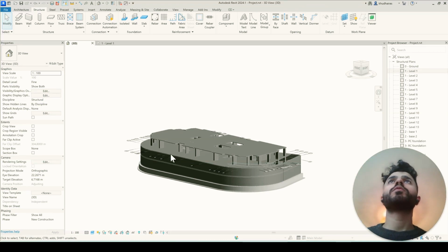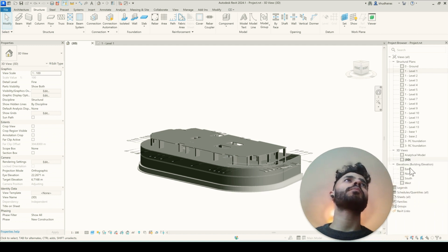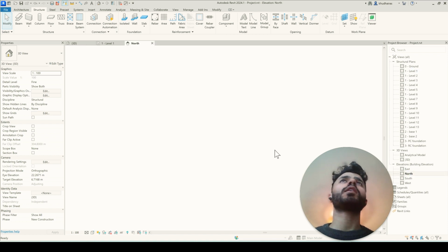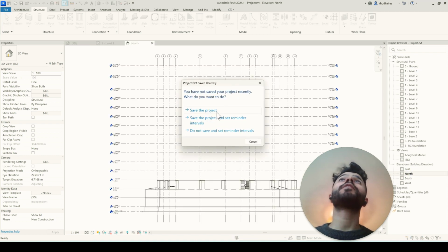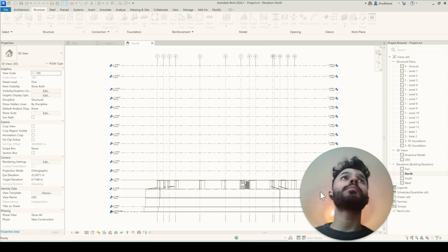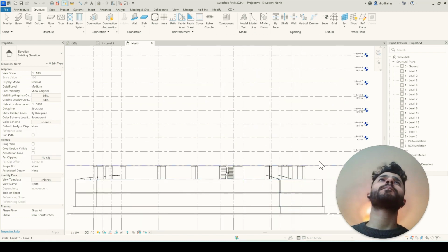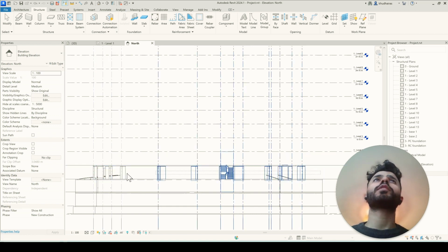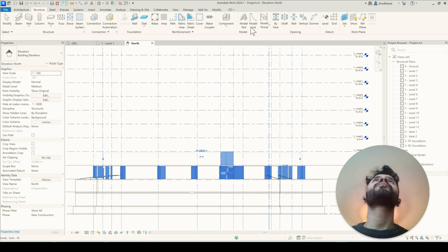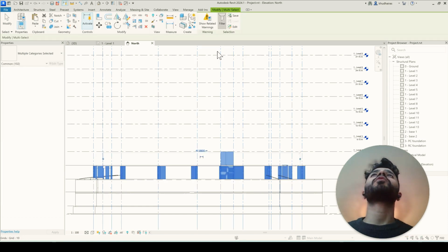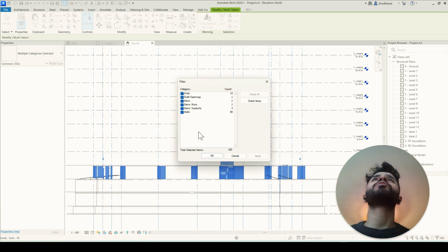Okay, so once you create one typical floor, you can copy that floor to the different levels. For example, if you go to north, and on this level the floors are typical. If they are not typical floors, it's better to do the common element, then you do floor by floor. So what I'll do is select all this floor, making sure I'm selecting only the objects that I want to go up.